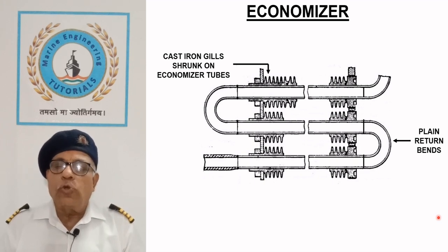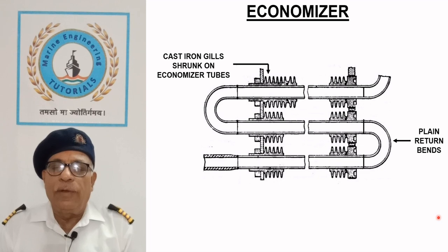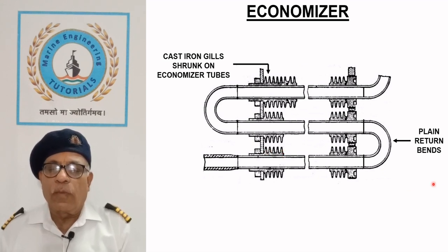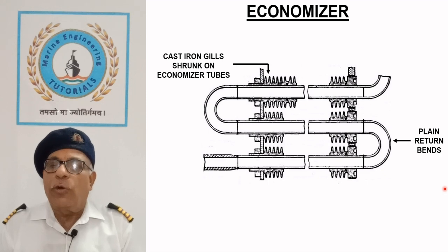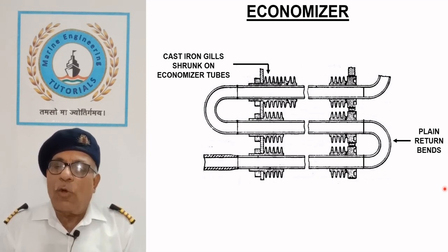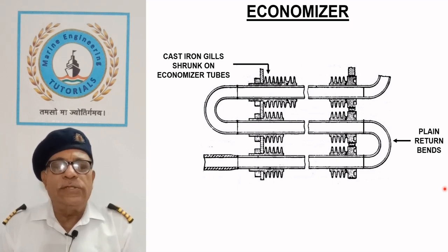The gills also improve the heat transfer due to an increase of surface area by about 6 times, but cause the deposition of soot due to restriction of gas passage. Low sulfur or gaseous fuels being presently used may not require gills, as in earlier years when diesel oil was used during engine part load operation with plain tubes.